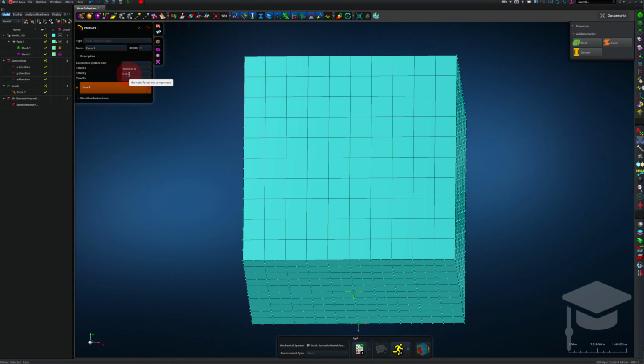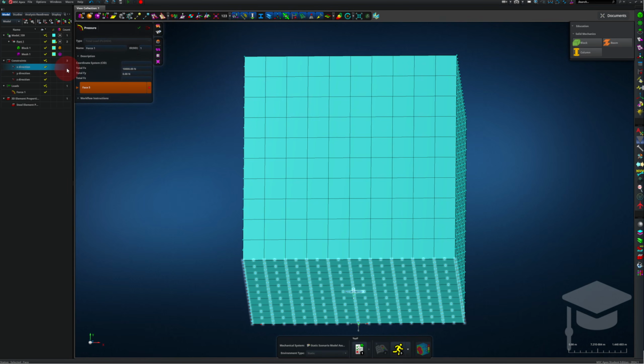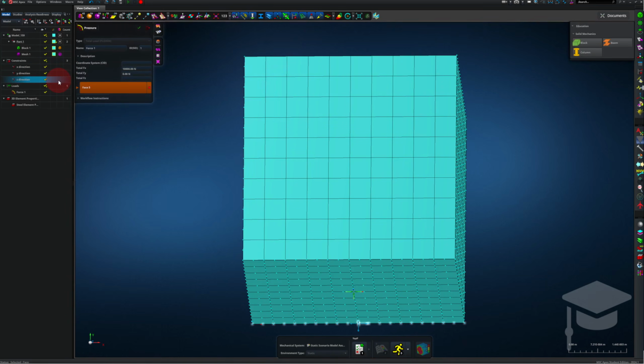We don't expect the bottom surface of the block to change in size based on an applied shear load, right? Because it's not under tension and so it's not undergoing narrowing due to the Poisson effect. Therefore, we can constrain against x motion all along the bottom surface and that doesn't make a problem. The z direction constraint is unchanged.